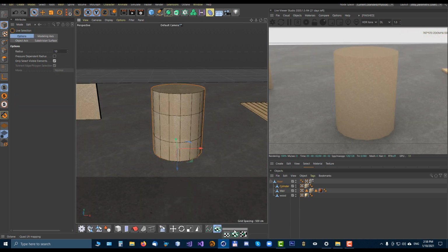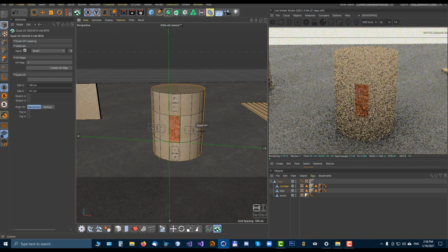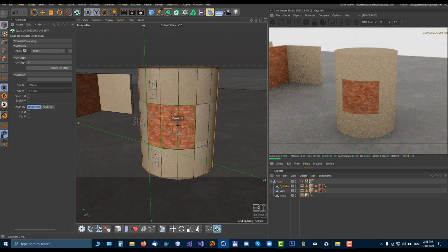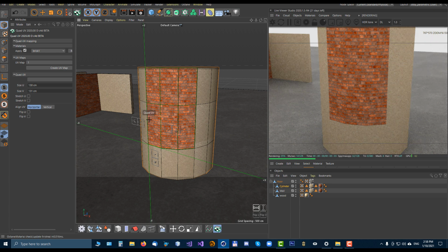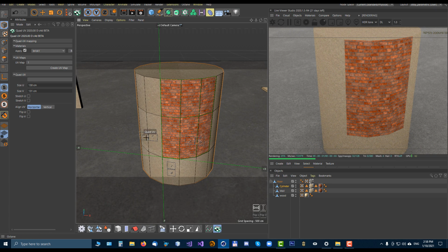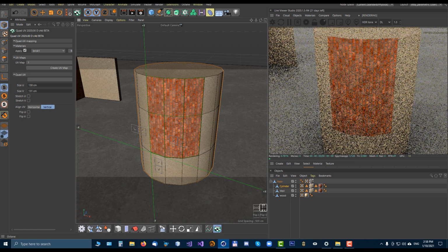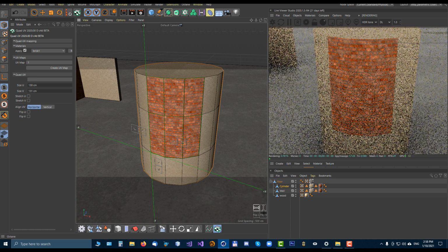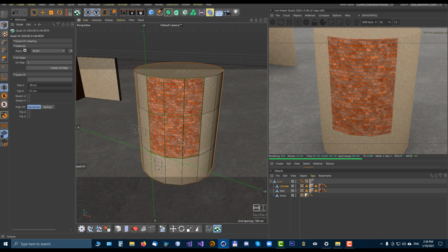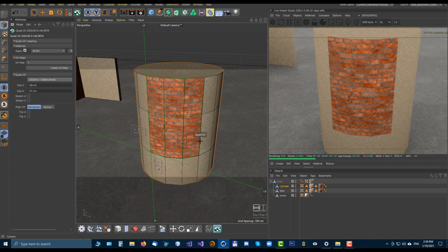The next very useful UV mapping tool is Quad Mapper. You can create and apply UV mapping on quads, and you can expand the selection on these quads, and the UV map will be stretched along this selection. You can change orientation, flip, and also you can use the same preset system to load back the size of the UV map which you have created with the rectangle tool.